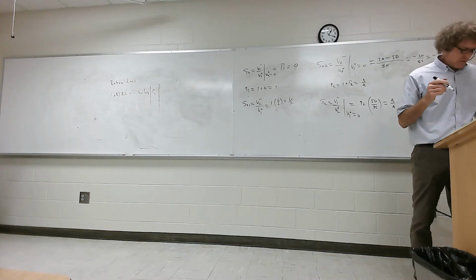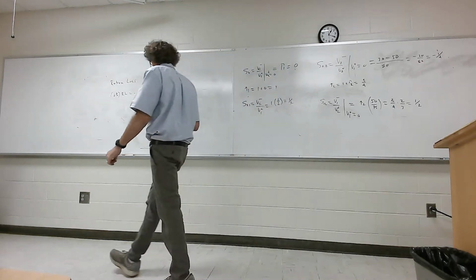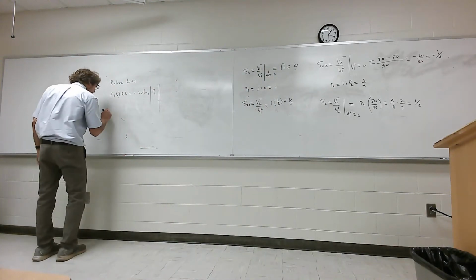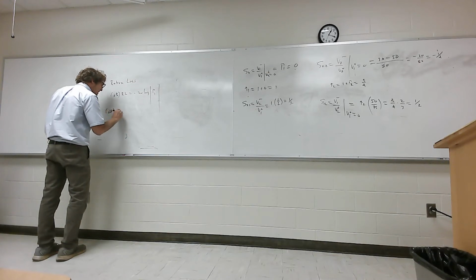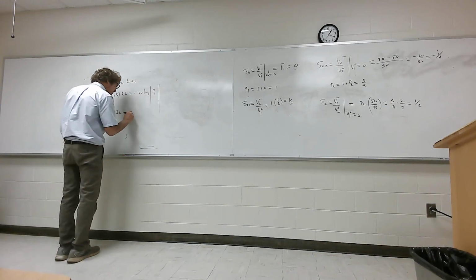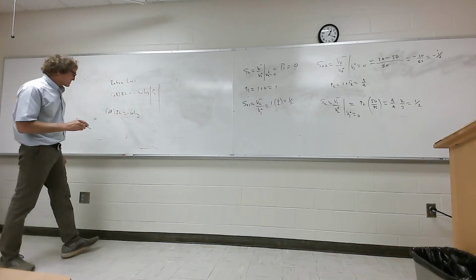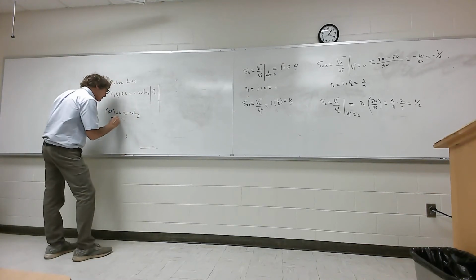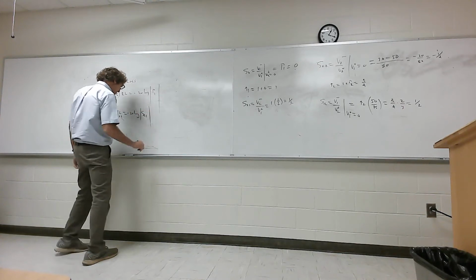Insertion loss is similar. When you do insertion loss, it's in dB as well. Same basic idea, minus 20 times the log. Now he doesn't put the S parameters, but I like doing it this way. He'll put ij, but for the 2,1, S21, it's just the magnitude of S21 right there.